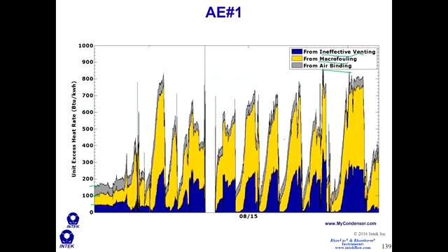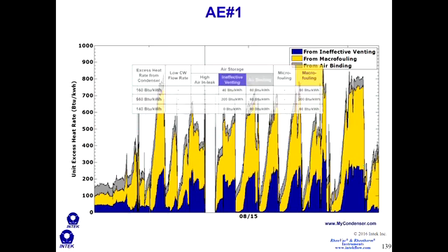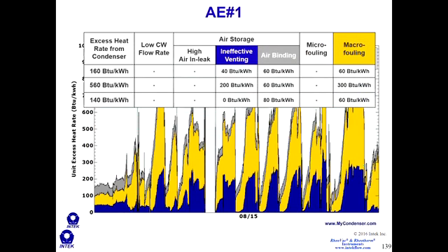Now this particular unit, the majority of the performance loss was due to macrofouling, but during that condition, their bundle became undervented, and so the macrofouling actually exacerbated some of the air binding in this condenser. So we made 2 major changes in this condenser. One was external to the vacuum equipment piping, and another change was to the condenser bundle itself to bring that airbound zone closer to the air removal section.